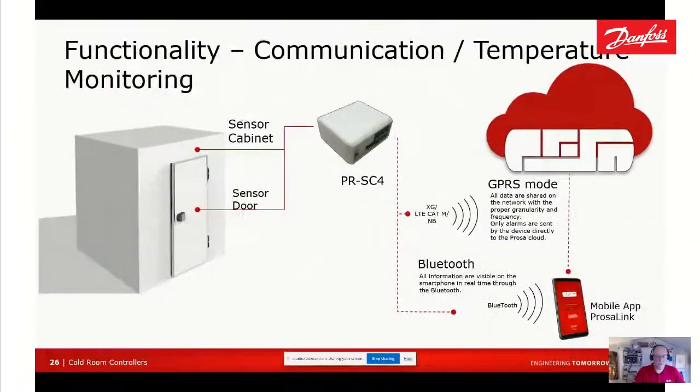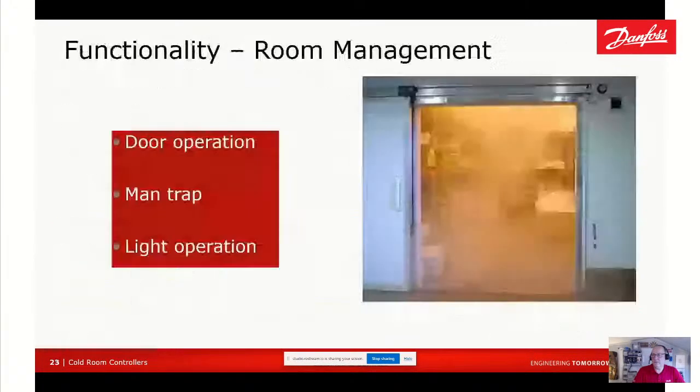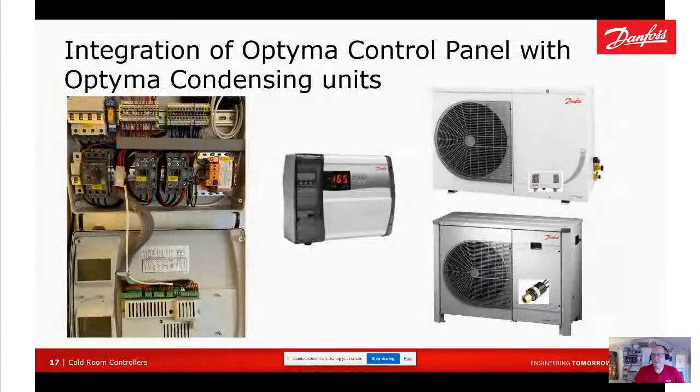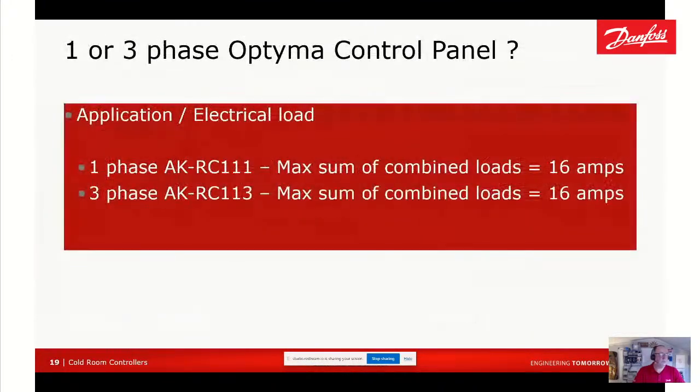All right, let's bob back to the slides a minute. I'll go back through some. We talked about that one, we talked about the loads. Loads is important, as I said. Make sure things like you can't have your defrost heaters running when the compressor's running, for obvious reasons. It's common sense, but these things do happen.